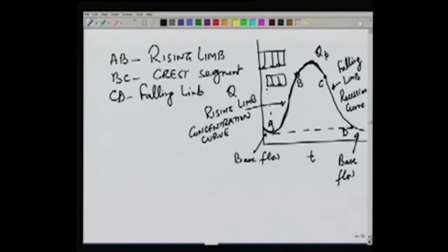From the point A, the effective rain starts, it stops somewhere, and the peak will occur after the stoppage of the rain, because when the rain stops, the areas which are remote from the point A would take some time for that water to reach the point A, and therefore the runoff will continue to increase even after a stoppage of rain.